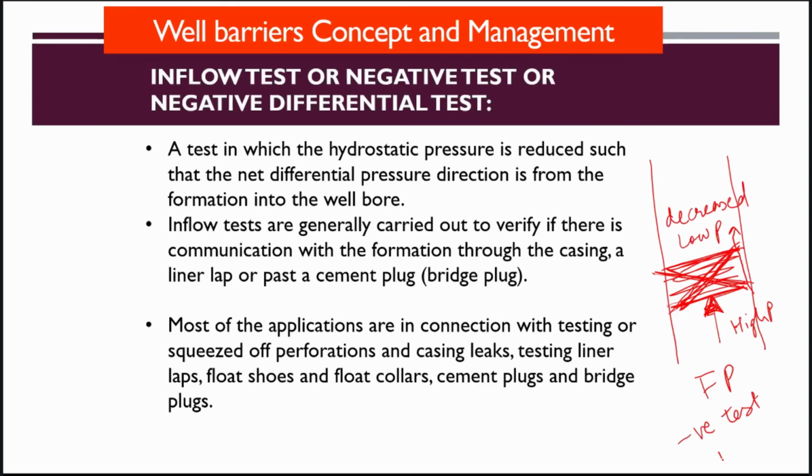negative test, or it is also called an inflow test. Inflow test means from below your pressure is high, downside of the barrier pressure is high, and upside of the barrier you decrease the pressure to check for any leak.